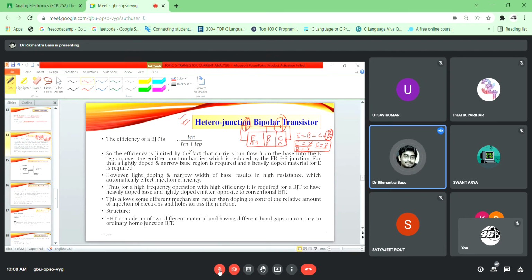If you recall, to operate a transistor as a switch we don't need to struggle much, because for the switch to be off the current is always zero, and for the switch to be on, check the manufacturer's data sheet, or apply the mathematical equations, just push it into the saturation region so that the switch becomes on.